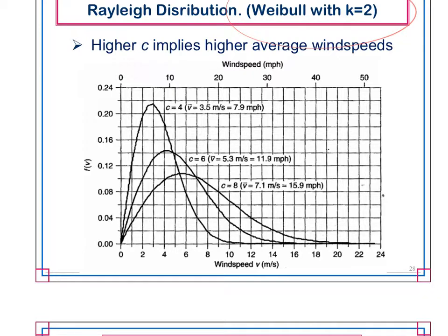It's all based on using a Weibull distribution, k of 2, and then you adjust the scale parameter based on what you expect the average wind speed to be. So if you have an average, you can just adjust your function. Is your scale factor 4, 6, 8, etc.